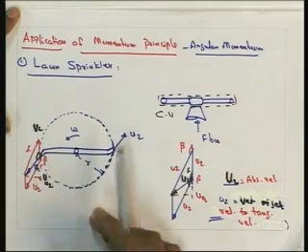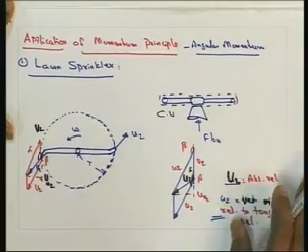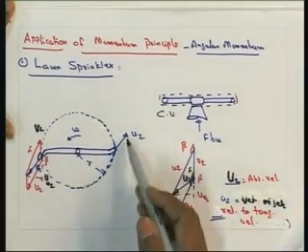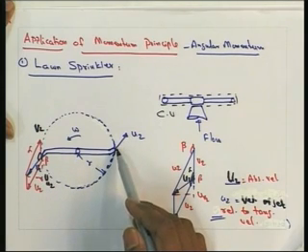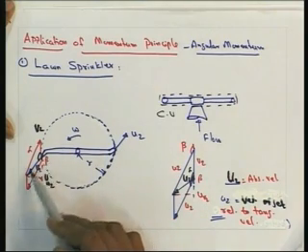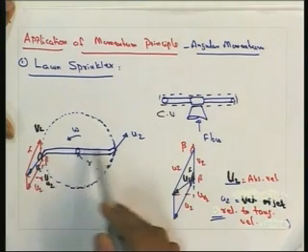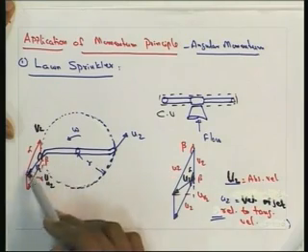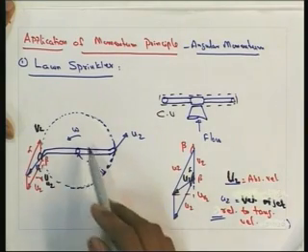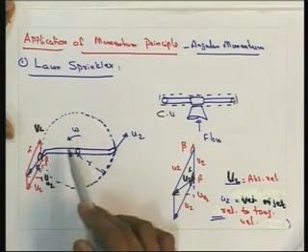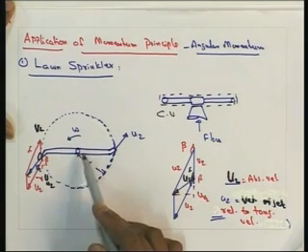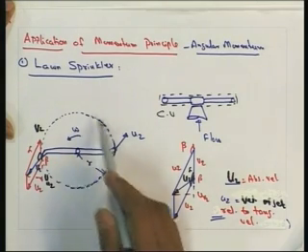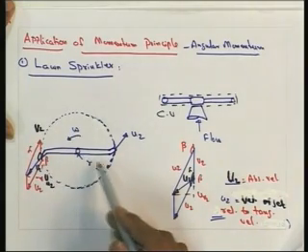Now if you consider the figure here, U2 is the absolute velocity of the water flowing through the nozzle, coming through the jet action here, and similarly on this side also. If you consider the symmetric case, this will be U2, here also it will be U2, and the rotation of the arm is omega, and R is the distance from the center line to where the rotating arm ends.